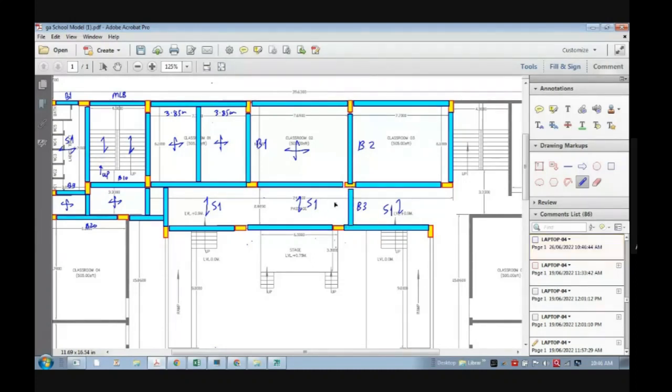Now, whatever I'm saying, please check in the software in ETABS. You will understand, because this you cannot understand by manually, but you should get a feeling by manual calculation. I suggest please do the model, at least one frame model, and then check the bending moments, and do this also B1 and check the bending moments.